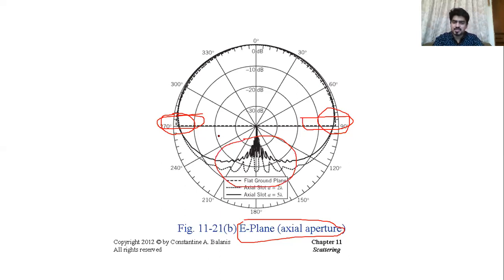Again, you see a similar trend that on the back side, since you have much stronger diffracted fields from the edges, those creeping waves create constructive and destructive interference, and you see back lobes in the rear direction on the back side of your cylindrical structure.